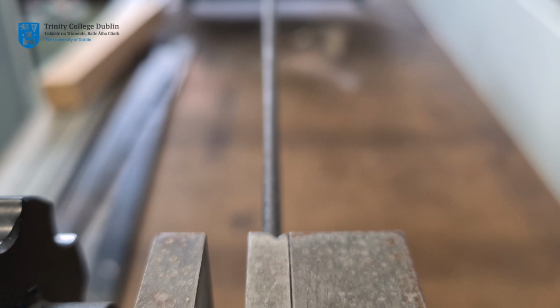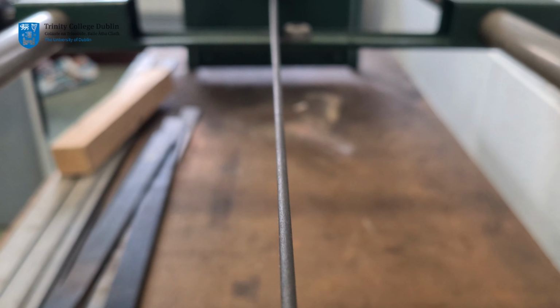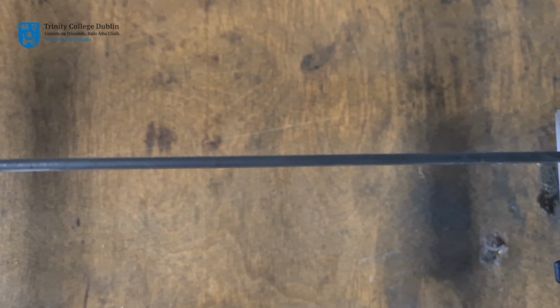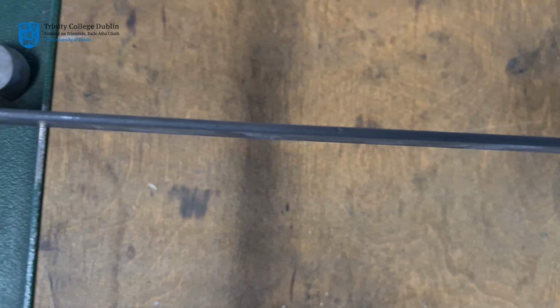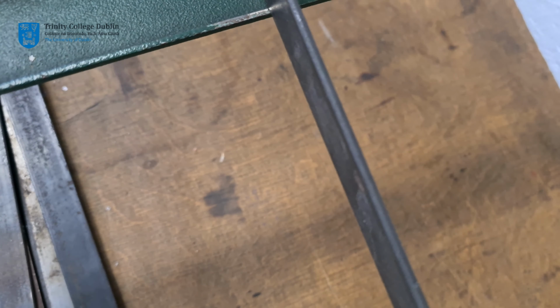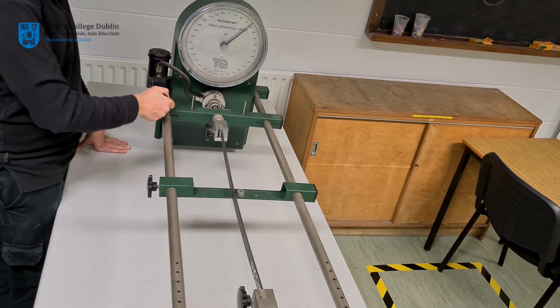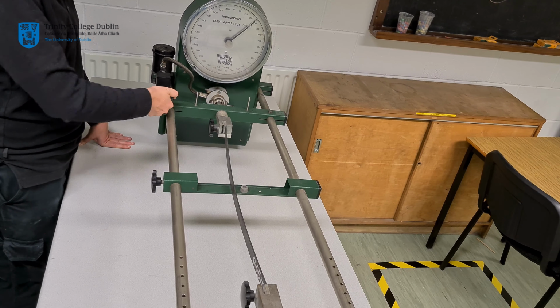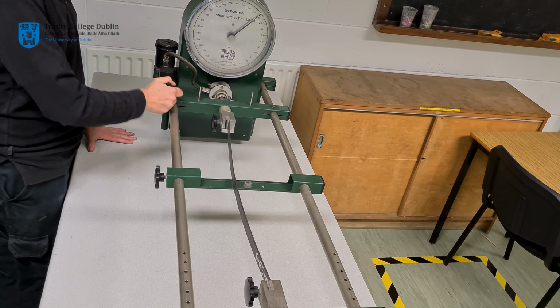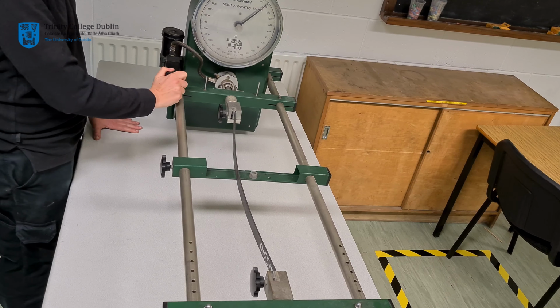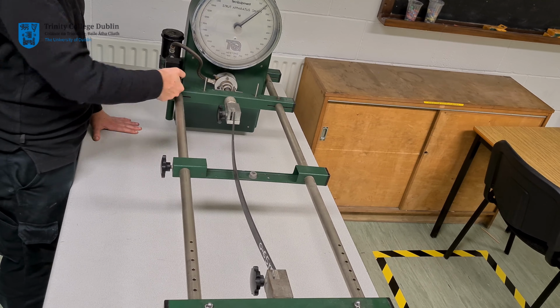Ideally speaking, a perfectly straight strut subjected to a purely axial compressive load would compress and not buckle. Buckling is therefore a result of imperfections in the straightness of the strut and/or eccentricity in the applied loading. Buckling is a form of instability. It occurs suddenly with large changes in deformation but little change in loading. For this reason, it is a dangerous phenomenon and must be avoided in structural design.